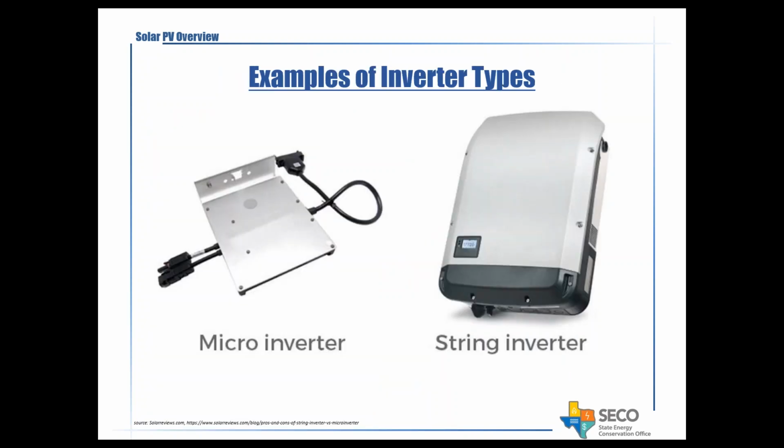So the next one of the main components of a solar system or a PV system is the inverter type. And what we want to go over today are the two main types of inverters that are available out there. There's microinverters as well as string inverters. For the microinverters, they're generally installed 1-to-1 with the panels, but they can be 1-to-2 or 1-to-4, installed directly under the panel. So you may have one microinverter for 2 panels or one microinverter for 4 panels, but typically they're 1-to-1. And the microinverters are wired or configured in parallel.